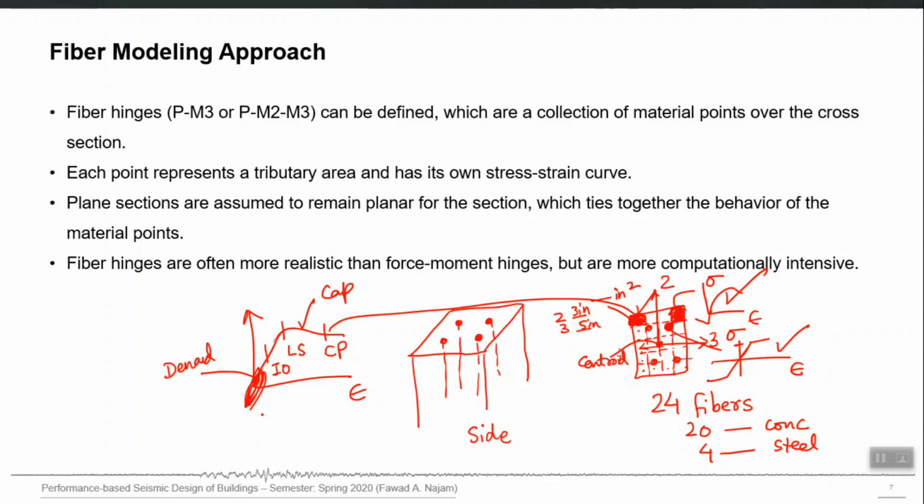So resultingly I will be able to exactly identify which fiber of which column will go beyond the cracking level of my stress, or ultimate f'c, right? Now remember that this stress strain curve is coming from an experiment ideally, right? So each point on that stress strain curve should have a visual picture in your mind of how concrete looks when it is here or here or here, right? So you have a picture of damage associated with each point on that curve, right?